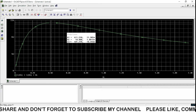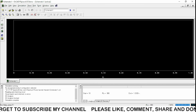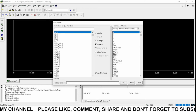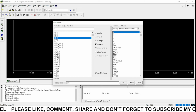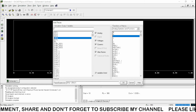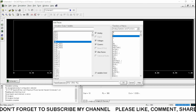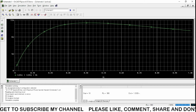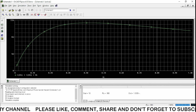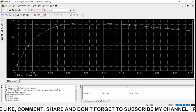So we'll get a graph. That graph will be a blank graph where we have RL only on the x-axis. So I'm going to add a trace. What is the formula for calculation of power? That is equal to I squared RL. I R4 is RL actually, I squared, and RL. So the formula is I squared RL. So IR4 into IR4 into RL, that is equal to I squared RL, and you will get the graph like this. You can see the power is very small close to zero, and it is maximum at this point.